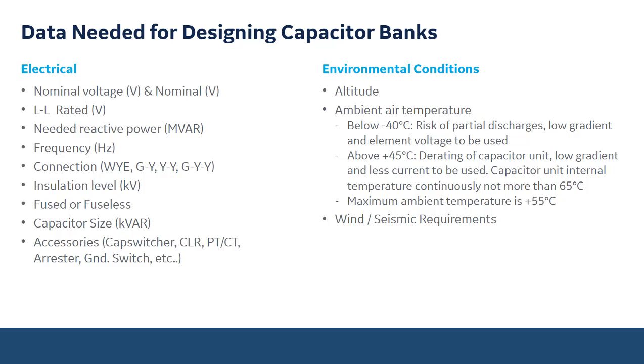And so here we get a lot of questions on how do capacitors operate at elevated temperature, and is there a life expectancy decrease due to elevated temperature? And this is something we get asked pretty frequently by a lot of our southeast or southwestern customers, and the answer is capacitors operate in elevated temperatures as expected. There's not really a decrease in life expectancy due to that elevated temperature. The dielectric oil in the capacitor is still viscous.